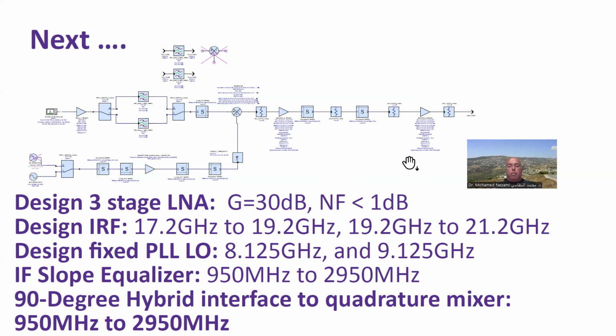That doesn't impact the regulation section, which regulates from say 15 or 18 down to like 3.3, 3, 1.5, 5 volt. That doesn't change because it's fixed. But you can utilize that as a switch to switch between bands.